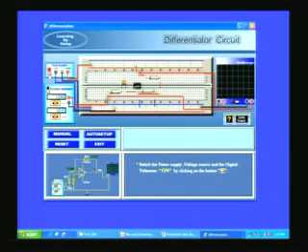Now I will switch on the power supply, the function generator, and the oscilloscope. If I now apply some 500 hertz or so and about 1 volt, you can immediately see that a triangular wave given as the input produces a square wave, and you can also see the amplitude is multiplied by 2 because of the values that I have used in this specific circuit. So a triangular wave given to a differentiating circuit should result in a square wave at the output. That is what I wanted to show you.